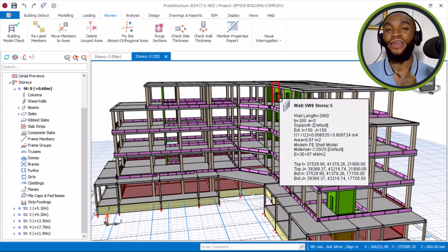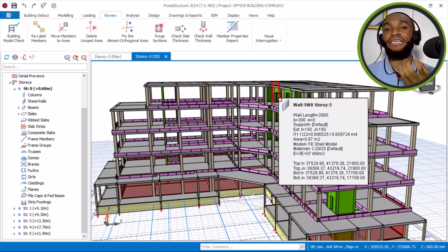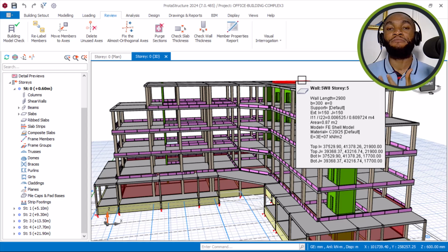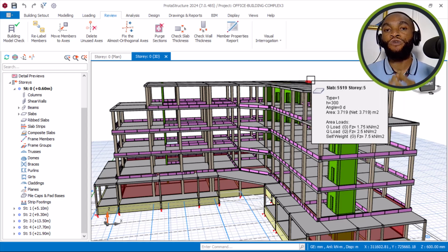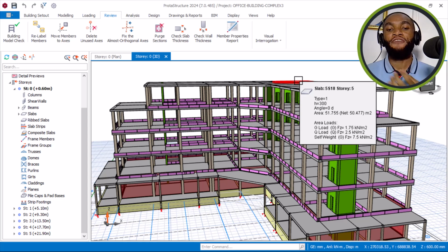Applying wind load to a structure below 10 meters is like wasting material for the client and increasing the cost of the structure, because the wind effect you have added results in bigger sections for your vertical members, like columns and walls, even though the building will not be exposed to any wind effects. Invariably, you have just wasted your client's money.